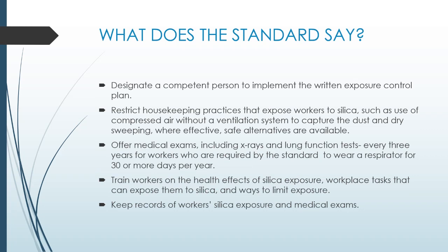We want to make sure that when we're cleaning up after ourselves, it even tells us how to clean up around silica. We're not going to use compressed air. We're going to use ventilation systems and HEPA filters, and we're going to sweep up after ourselves. But it's not going to be just dry sweeping.